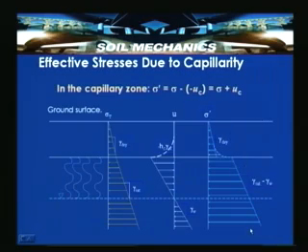So, it exhibits high effective stress at this particular zone, and then this particular variation is resulting due to this particular distribution. One has to keep in mind that this capillary saturation is generally not kept in design, because in the case of flooding or evaporation, when this is evaporated, this effective stress can be lost. As it is subjected to climatic conditions, it is very difficult to consider and keep this in the design.